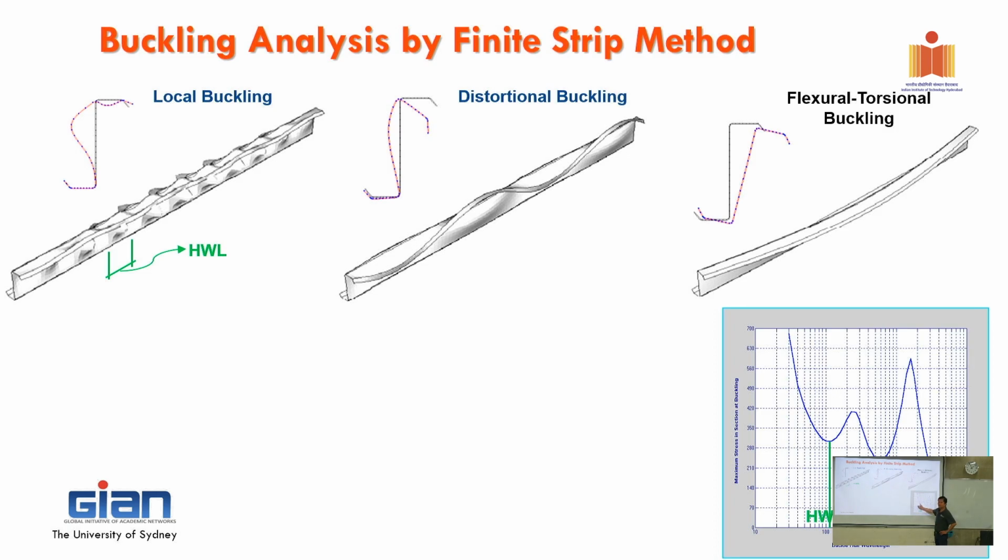You mean on the left side? The halfway length? When you go smaller than that, the stress is higher. We need a minimum point when it gets to the critical one. So normally when you push that one, it will fail and go to the bottom here. That means that it's 200. And then later on, you might play with that, put a little bit of stiffener, then it might change the halfway length a little bit. Maybe it's 220 or something, not 200. That's good practice for you to play and understand. So that is 200 now.